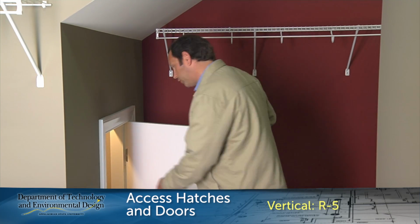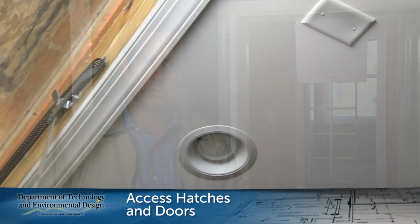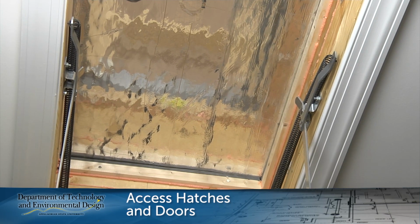All access hatches and doors must be weather stripped and insulated. Vertical access doors, such as this factory-built access door, only require R5 insulation. Horizontal access doors require R10. However, one exception is that pull-down stairs shall be insulated to an R5 insulation value. Remember that non-rigid insulation materials are not allowed, but that insulation systems such as attic hatches that enclose the stair system are allowed. If exposed foam plastic is used on any access, be sure it meets the provision of North Carolina Residential Code. 1102.1 also deals with ceiling insulation requirements.